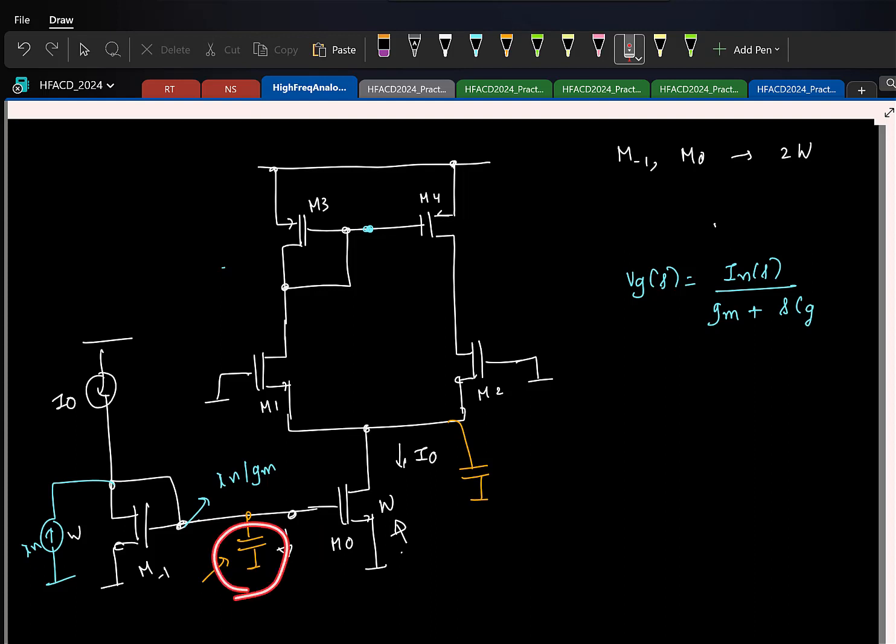If I go and put a large capacitor there, that capacitor is going to get charged to the required voltage. That is going to act like, loosely speaking, a battery there, right? For any DC point, if you put a large capacitor, it's actually good. So this cap might not impact you so much. But let us say this cap increases. What can go wrong?